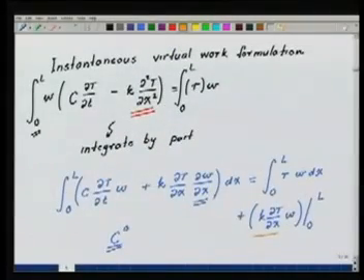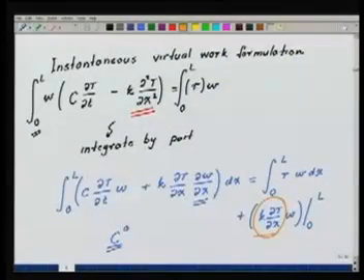So at x equal to 0, W is 0, so that part gets cancelled out. At the other end, at x equal to L, we have k del t del x, the flux condition, given equal to G. So we have exactly the same boundary conditions, that is the flux at the end x equal to L and the temperature at end x equal to 0. So this whole thing will be equivalent to G into W at L.